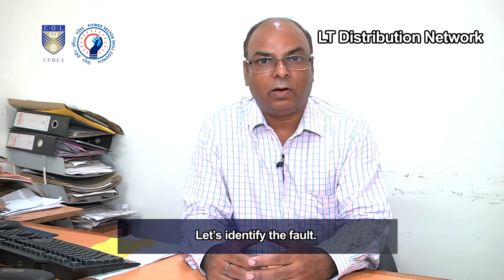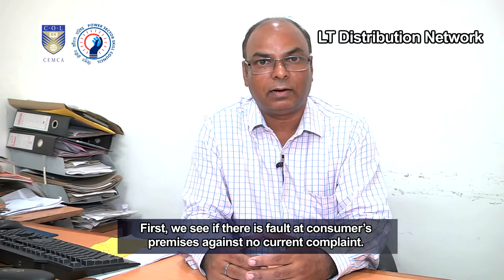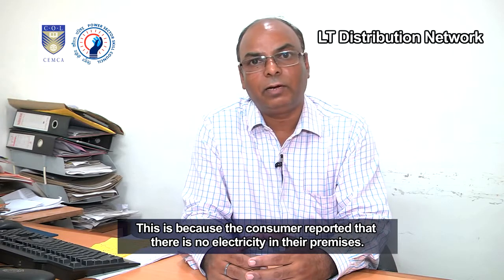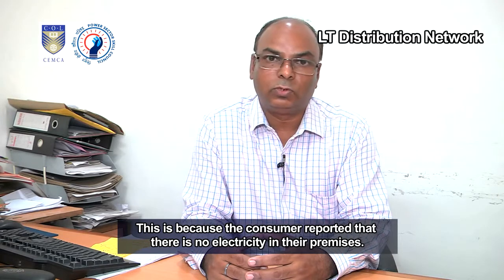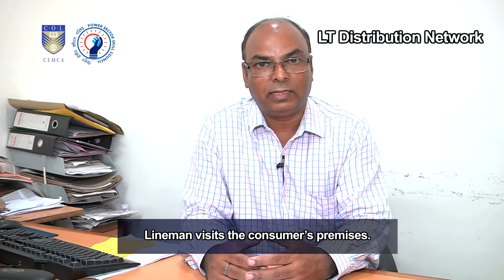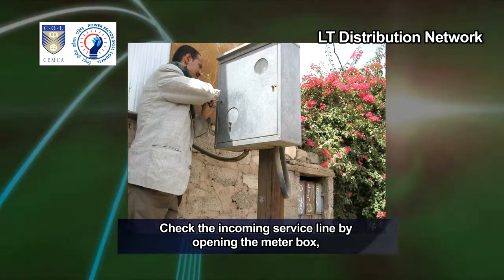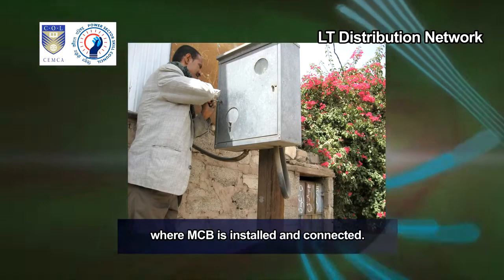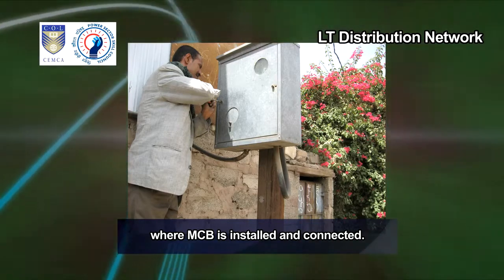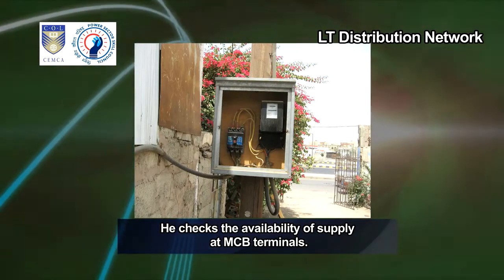Let's identify the fault. First, we see if there is fault at consumer's premises against no current complaint. This is because the consumer reported that there is no electricity in their premises. Lineman visits the consumer's premises. Check the incoming service line by opening the meter box, where MCB is installed and connected. He checks the availability of supply at MCB terminals.